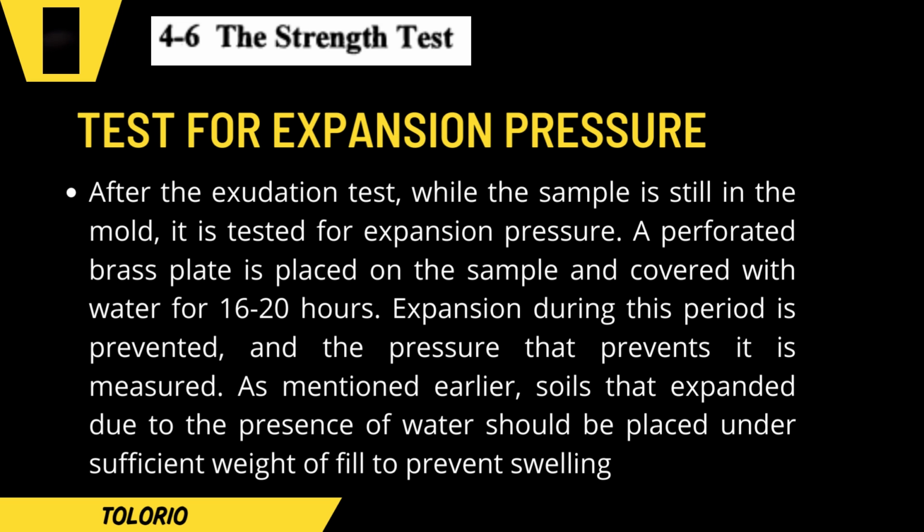Expansion during this period is prevented and the pressure that prevents it is measured. As mentioned earlier, soils that expand due to the presence of water should be placed under sufficient weight of fill to prevent swelling.